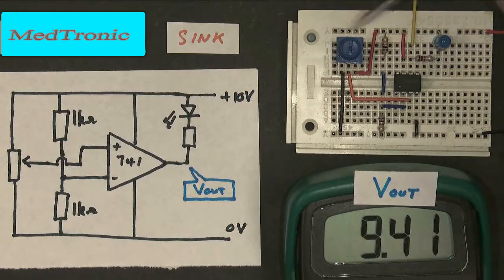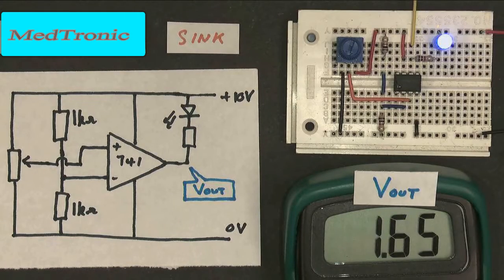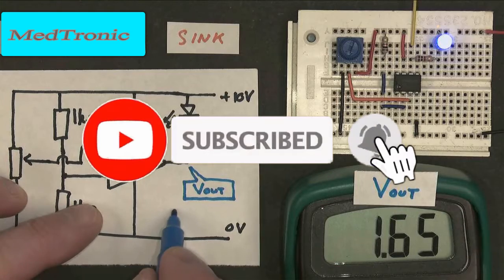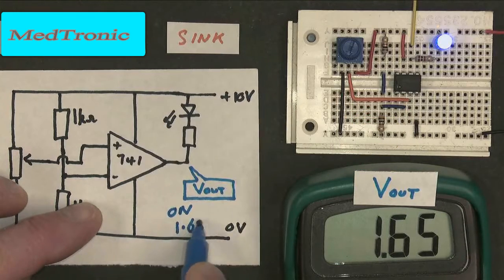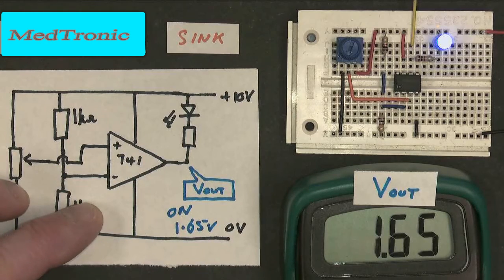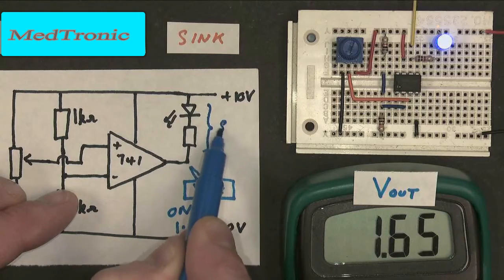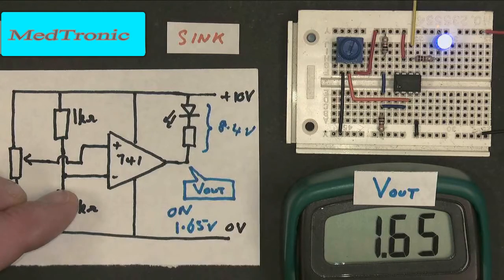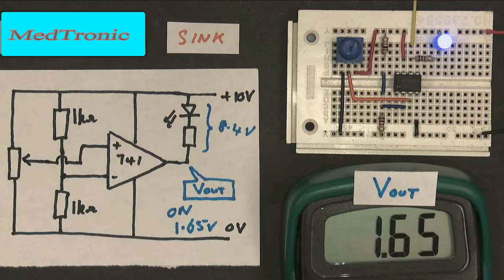So if we adjust our potentiometer circuit, our potential divider circuit again, the op-amp responds, and what we find now is that the output voltage has gone down to about 1.6 volts. So this time, when the LED is on, the output is about 1.65 volts or so. And that means that the potential difference across here is around about 8.4 volts. And that potential difference means that current can flow. But the question is, where does the current go?